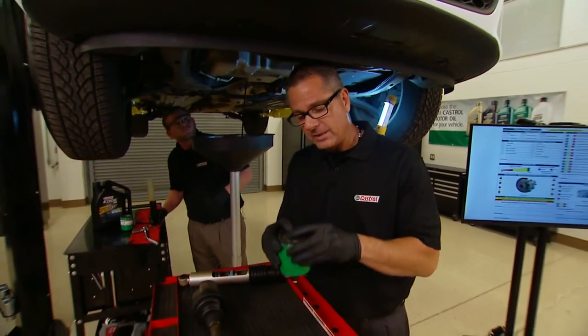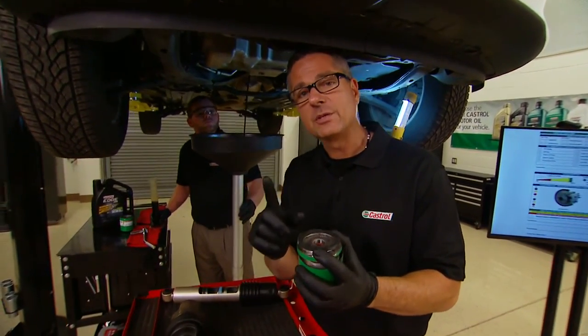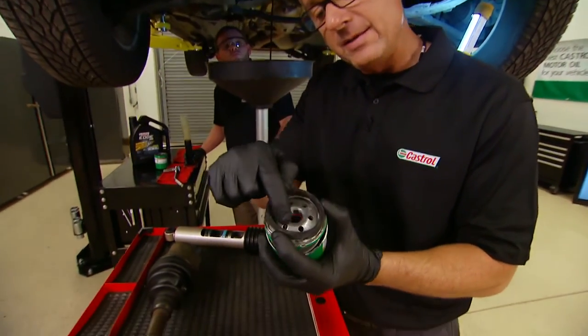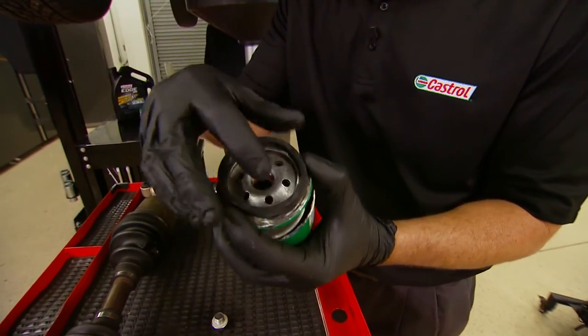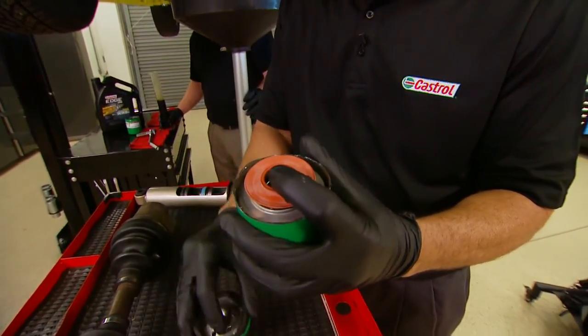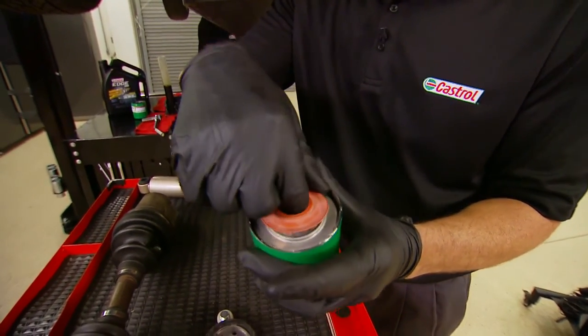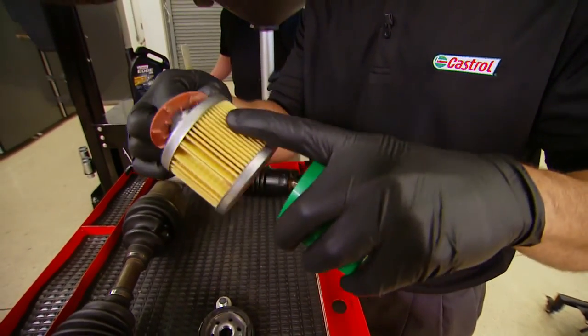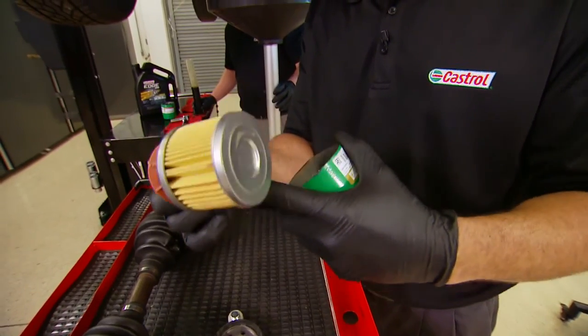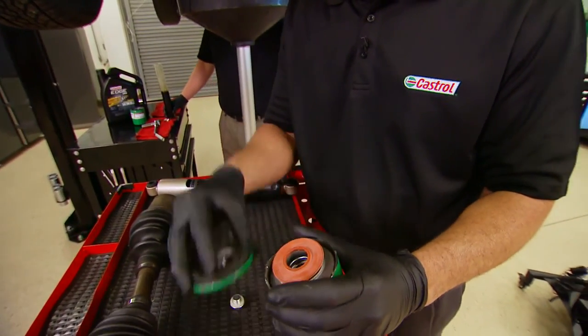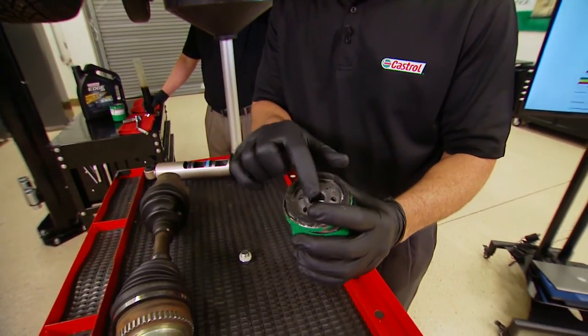Now I also have a cutaway of an oil filter. What's happening with the oil, it's actually going through these little holes right here. When it goes through these holes, it's going to go here through the anti-drain back valve. And then when it goes past the drain back valve, it runs along the outside of this filter material here. And then it comes back up and goes to the engine clean from the center here.